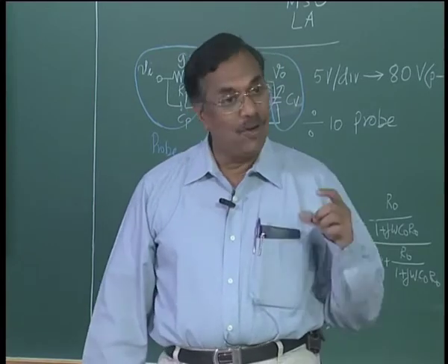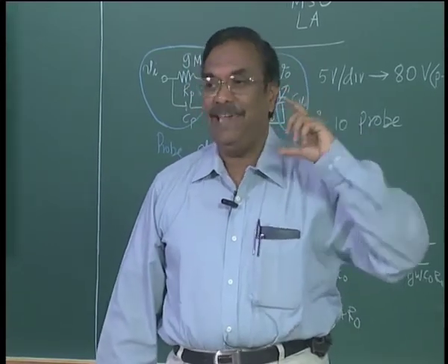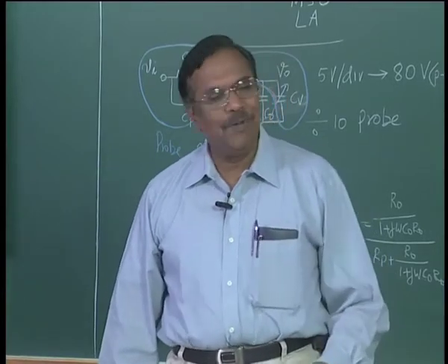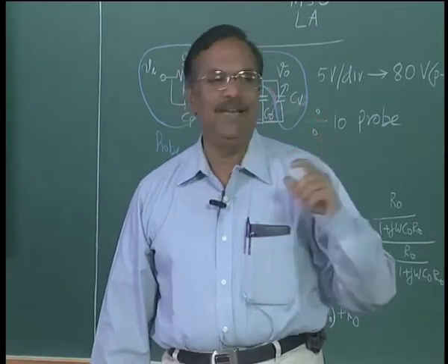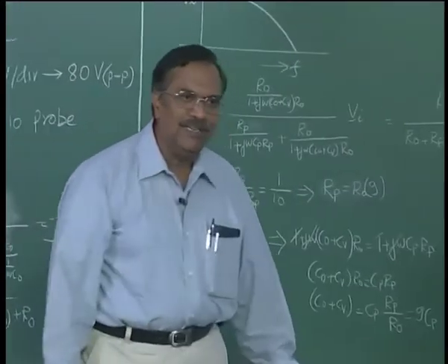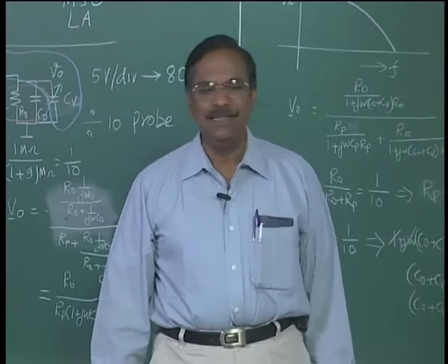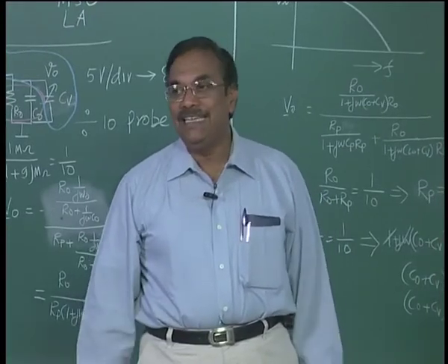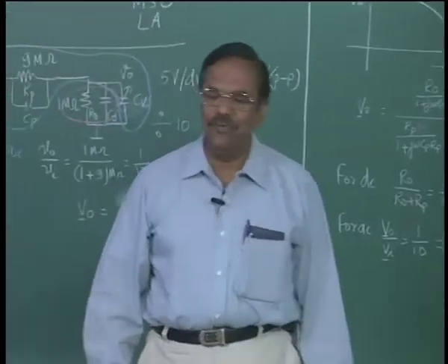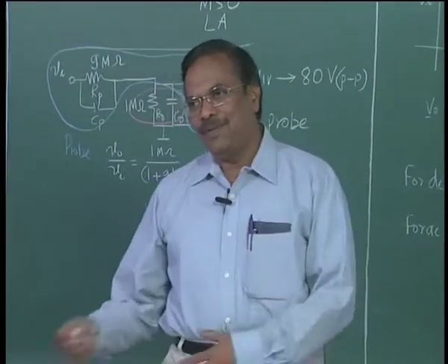So you can also check the Y calibration, right. You know it has to be 1 volt, and if you put 1 volt per division, I must get 1 division. If I put 500 millivolts per division, I should get 2 divisions, right. So that also can be checked on the oscilloscope. Some oscilloscope manufacturers also give you 100 millivolts apart from 1 volt.